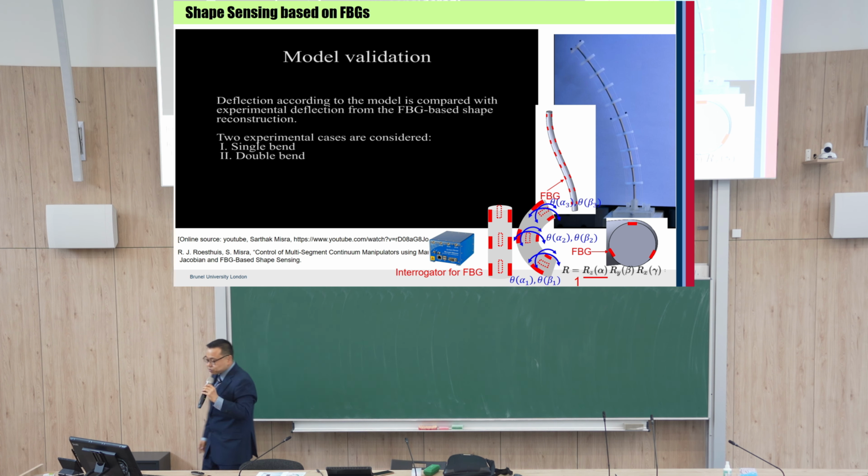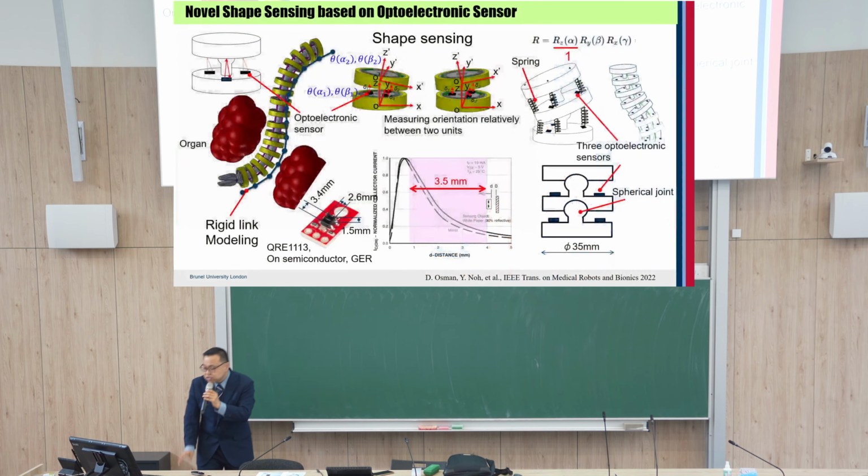That's the reason. And I can tell you this also: to attach all these FBGs to this elastic material, you have to do it manually. But for example, you successfully mounted 7, but 1 failed. Then you have to remove all of them. Why? Because the sensors are all serially connected. For that reason, if one sensor is broken, then you have to change all of them. So this is the reason this is not really good. That's the reason.